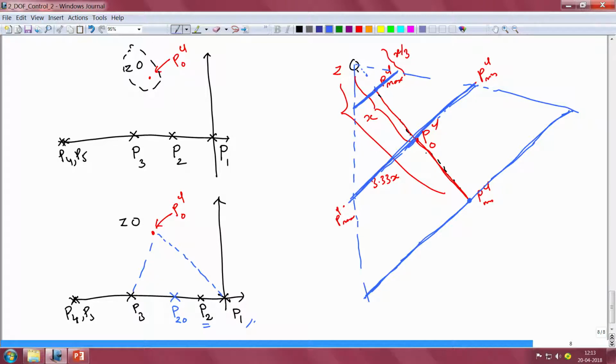Now continuing this argument further, we can see that for some other value of the gain of the plant, which is in between the values 0.3 and 3, our closed loop pole position would be at some other location on this red straight line. It would be at some other point here, which I have indicated by this green point, in the absence of uncertainty in the pole position.